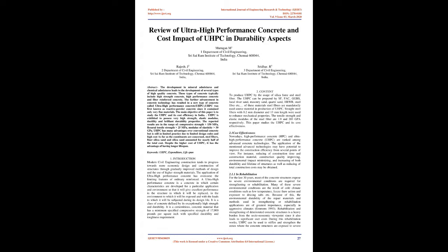UHPC was first known as reactive powder concrete since it contained only very fine materials. The main objective of this paper is to study the UHPC and its cost efficiency in India. UHPC is exhibited to possess very high strength, elastic modulus, ductility, and brilliant durability properties. The reported results are in the range of compressive strength 150 MPa, flexural tensile strength 25 MPa, modulus of elasticity